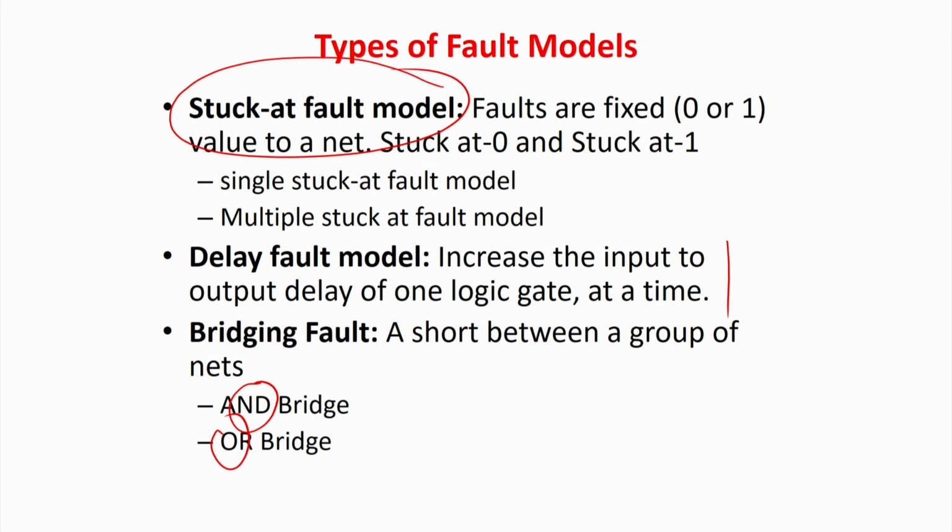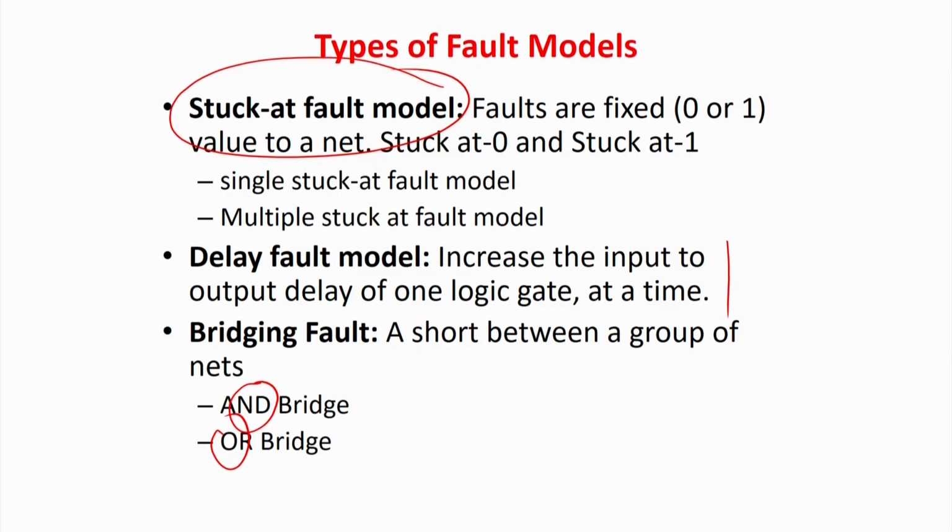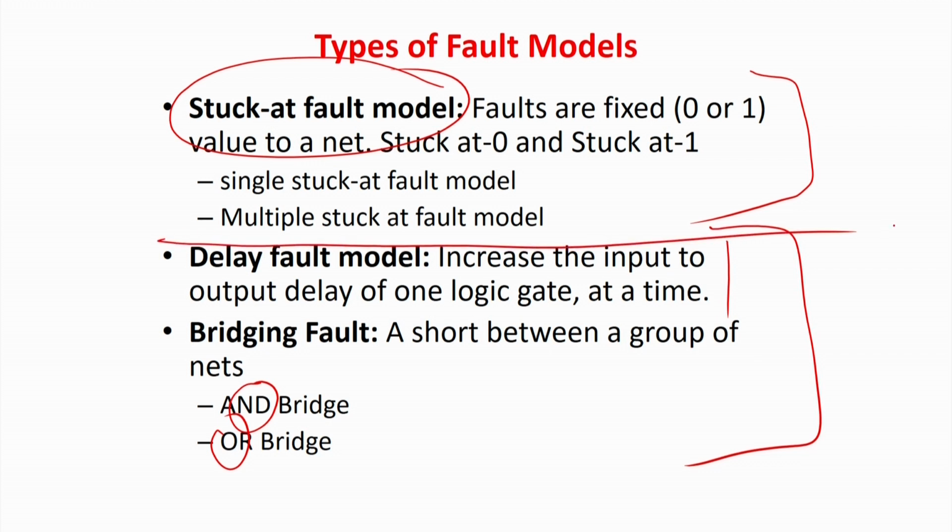Now, your job, as we will see, is just to verify that none of the gates have faults. In the current discussion we will be studying only this. Whenever we talk about advanced fault models in this course, we will go for such more advanced faults. But today our discussion is mainly limited to stuck at faults, because this is the most widely accepted, and until about 15 years back, this was the only fault model practiced. With more sophistication in fabrication technology, advanced fault models also had to be considered. So, the stuck at fault model is very simple. You assume there is a line, and the line is either stuck at 0 or stuck at 1. So, it captures a huge number of defects.